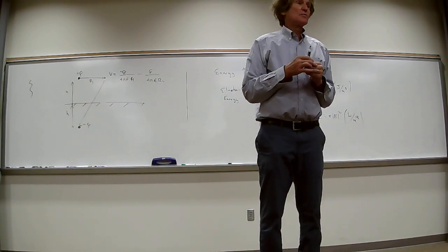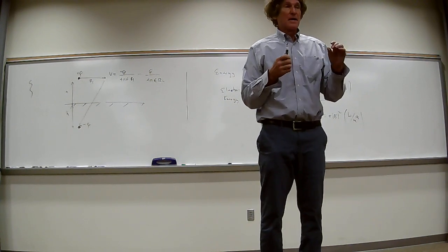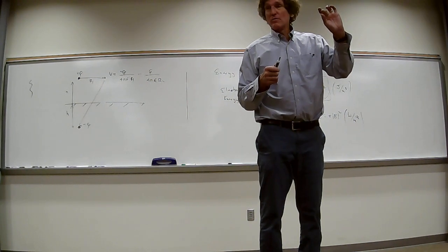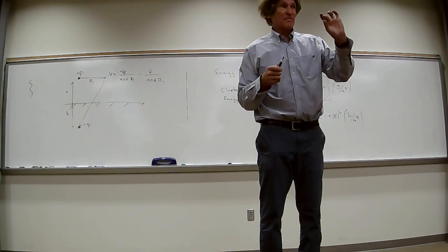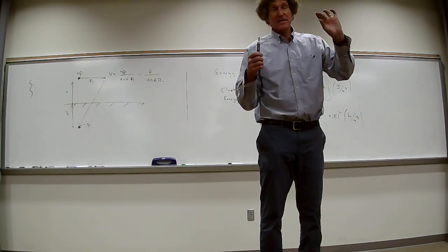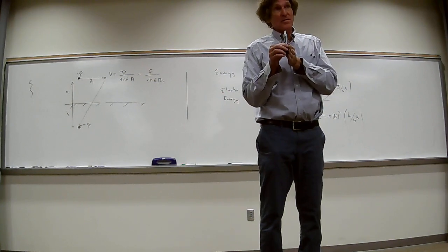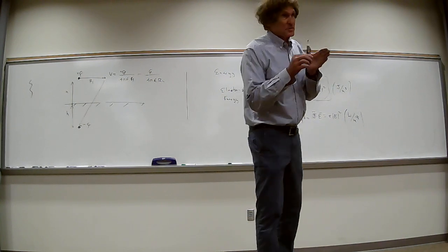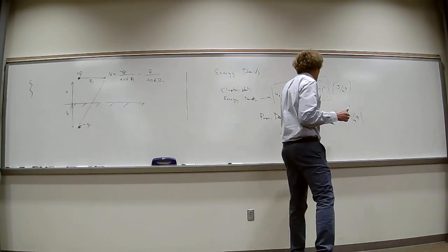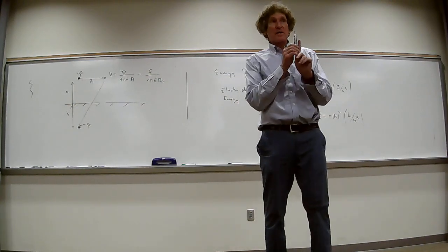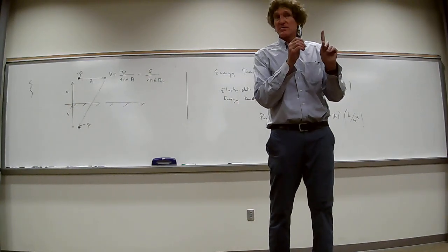It's about 3 million volts per meter. Sounds like a lot. But when you get down to stuff where you talk about volts per millimeter, now we're getting about hundreds of thousands, which are not that hard to attain with antennas. But there's a limit to the amount of power you can radiate from an antenna that deals with both the power density and the electrostatic energy density because of the maximum value of the electric field before you get corona discharge.